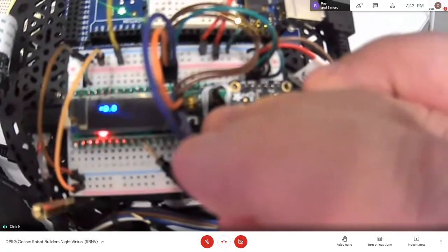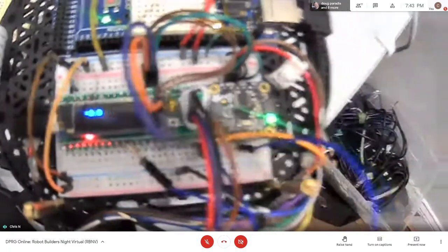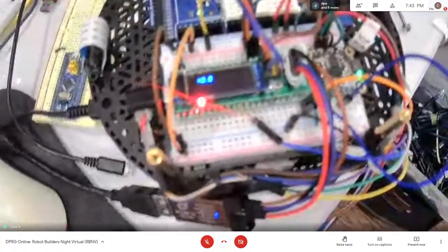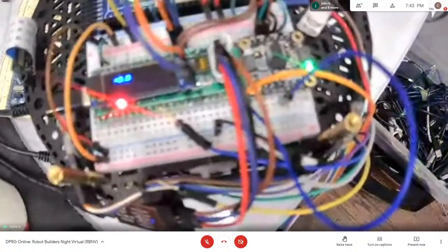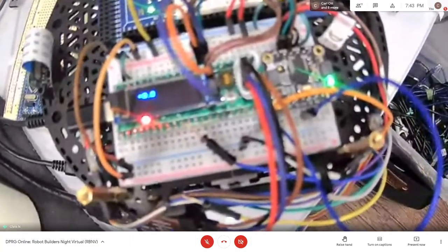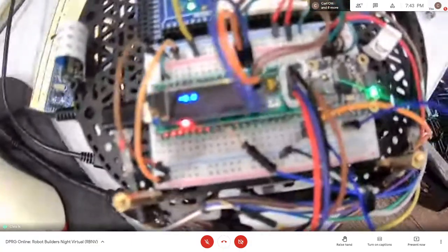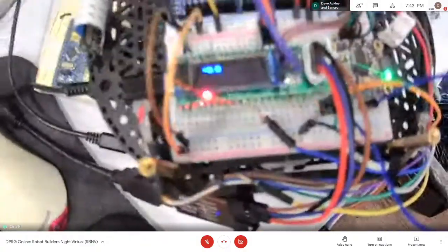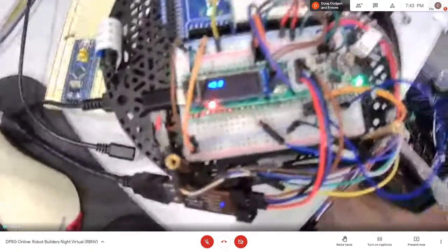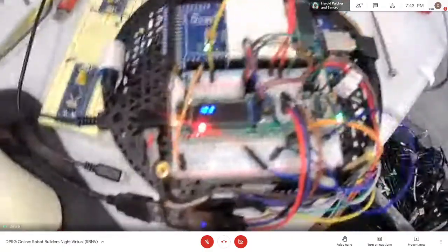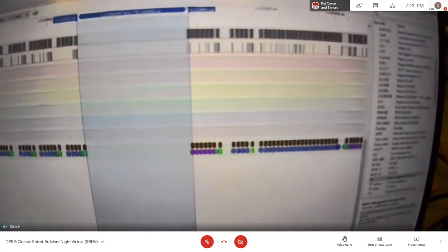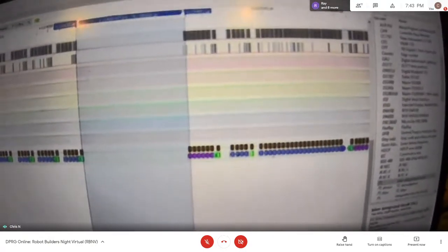But if I keep hitting reset here, I think I'm having a little more luck now, because what I actually did is, now I'm explicitly resetting the BNO using its reset input, rather than just leaving that reset input so that it's not in reset. I'm now explicitly resetting the BNO, taking it out of reset, and then start talking to it. That seems to help. I'm still not at 100%, and I don't have a trace up on the screen. This trace actually was a successful one, so I don't have an error case on the screen right now.